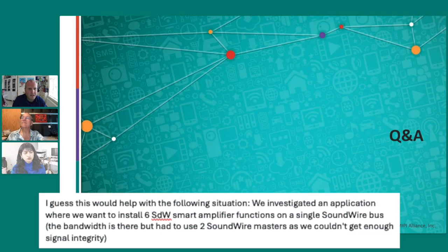I guess this will help with the following situation. We investigated an application where we want to install 6 SDW smart amplifier functions on a single SoundWire bus. Bandwidth is there, but we had to use 2 SoundWire masters as we couldn't get enough signal integrity. So I guess maybe this is a justification for...